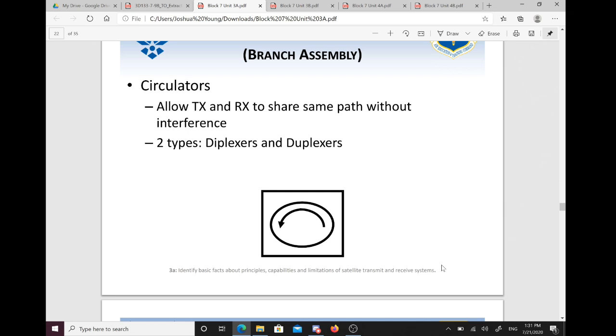Close. So y'all have heard of full duplex, half duplex, and simplex, right? So your diplexer's job is to be kind of like a traffic cop, right? So you can either transmit or receive. If your equipment uses a diplexer, the diplexer is responsible for saying, all right, are we transmitting or receiving right now? Transmitting, cool. But we're shutting off this receive circuitry in the meantime so that transmission can occur. And then after our data transmission is sent and we're required to receive, it does the inverse. It'll shut off the transmit circuitry so that the receive circuitry is open for reception of that transmission from